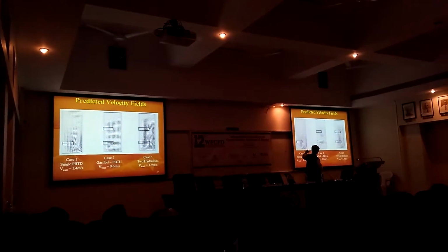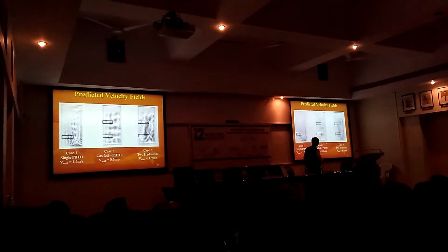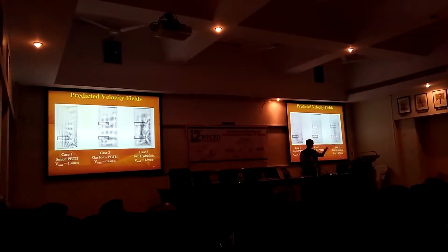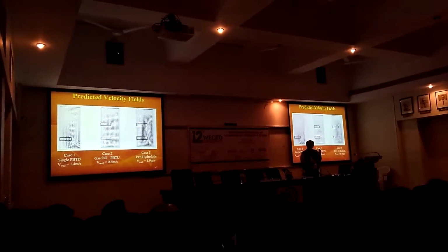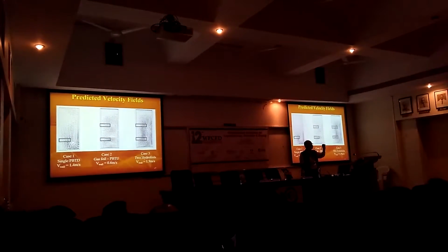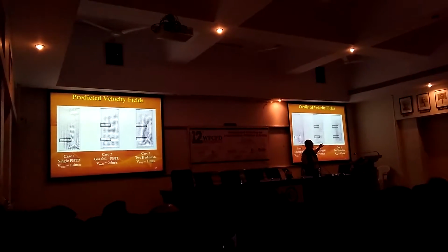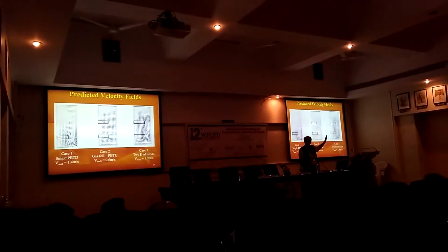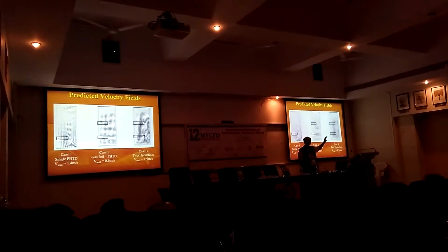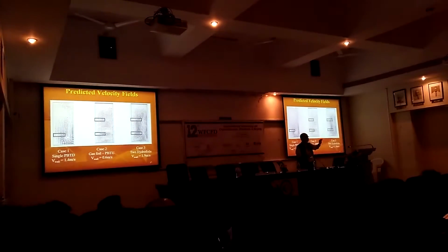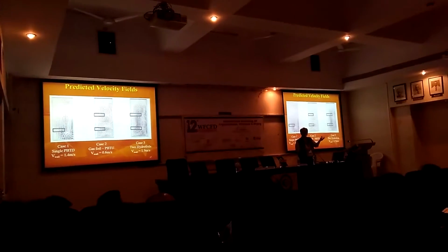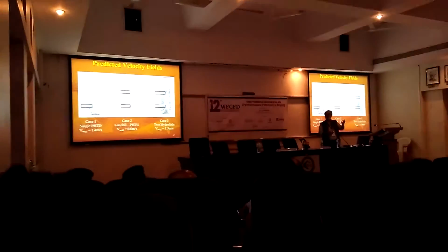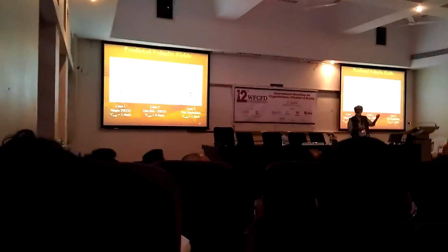So I can generate a sort of flow pattern, and this flow pattern, very similar to what Gauti was talking about, you can digitally design it. Now this is a digital design of the impeller. You need not carry out experiments. You can do these experiments on a computer and decide which particular flow pattern or which particular type of impeller is going to be ideally suited for the kind of application which you have in mind.